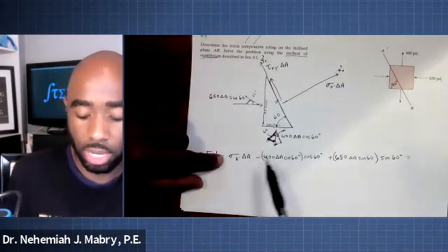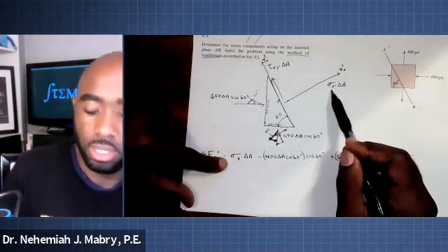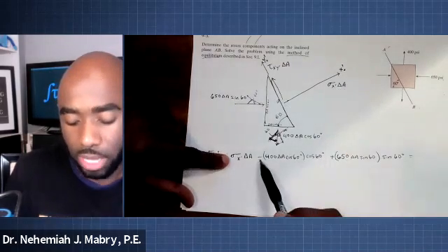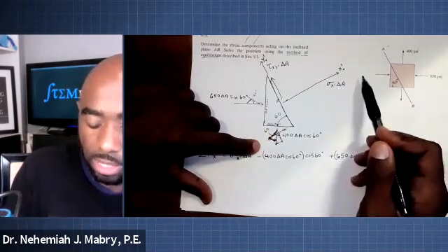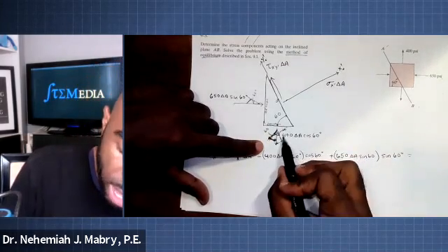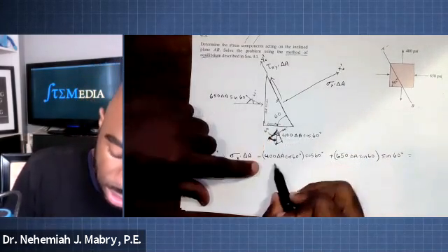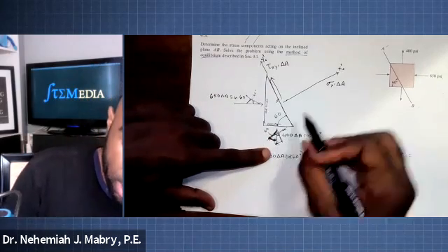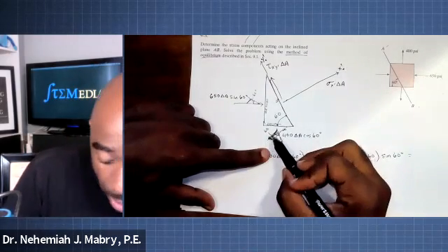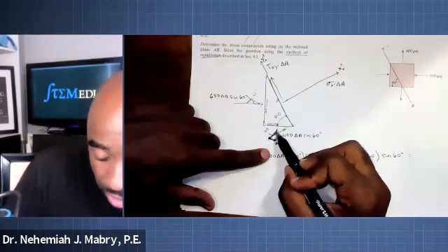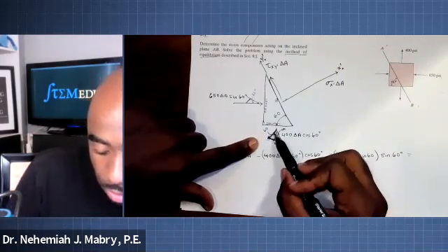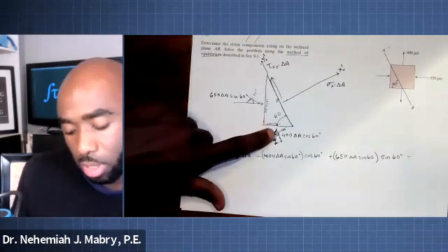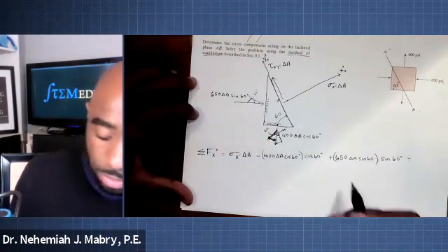I'm going to go ahead and do this again. We're looking at this direction, sigma sub x prime times delta A. Then we're going to look at what is attributing in this positive direction. Well, when we look at the values, it's going to be 400 delta A cosine 60, which is that. But we need the x prime component. The x prime component is this face, the cosine of 60, when you look at how the angle rotates out from that component.